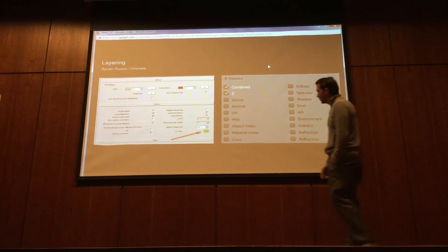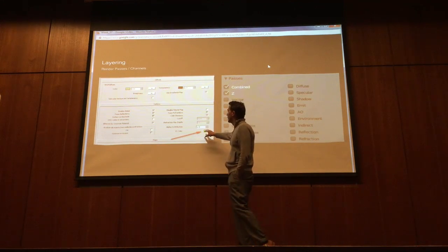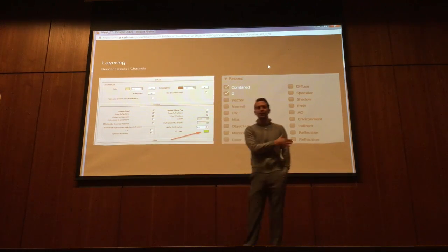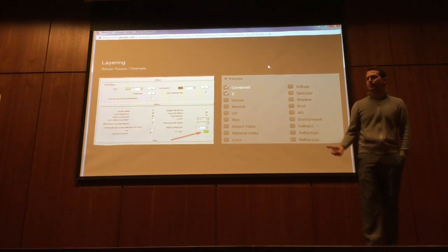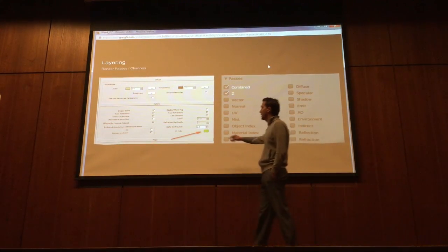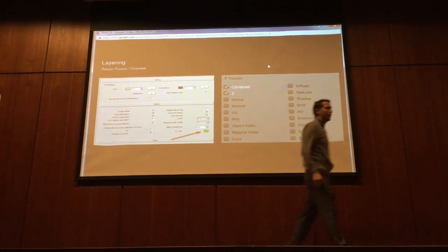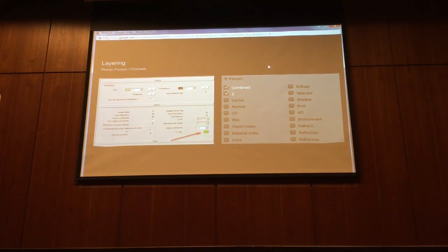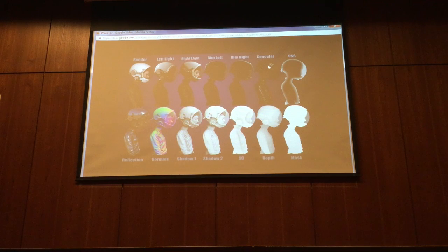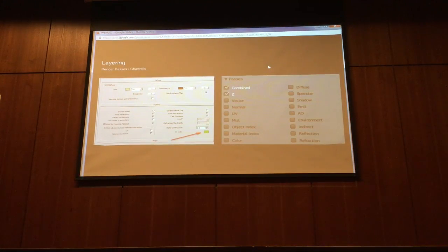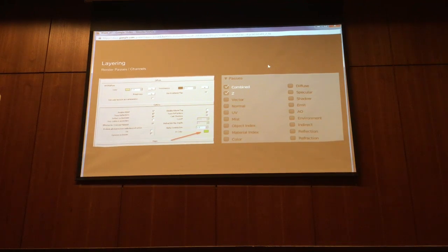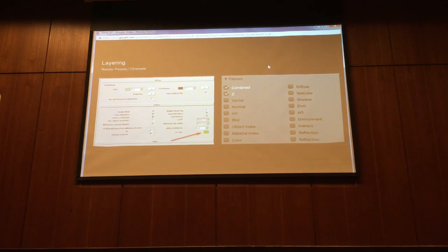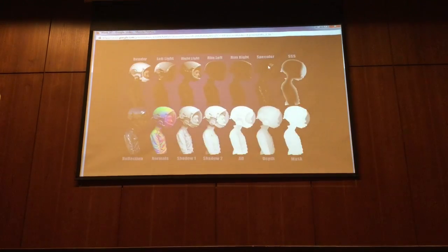One thing I would want to point you guys to is, even now, if you're rendering everything, you should be rendering everything in gray, right? You could create multiple gray materials and give them different color IDs because that will help you as you move into Photoshop. But the other thing, so the computer, when you hit render, if you don't have these checked, it is still going to run it. It calculates the diffuse, the shadow, all the specular to make your final output image. It takes slightly a little longer to get all those, but not really. And then you can have more control when you move into Photoshop.